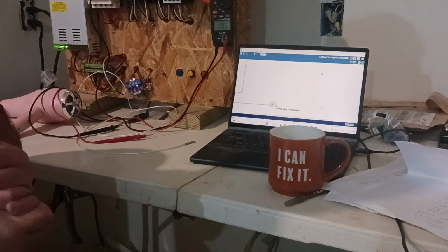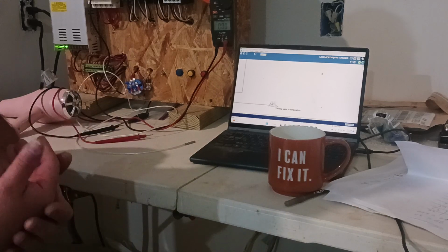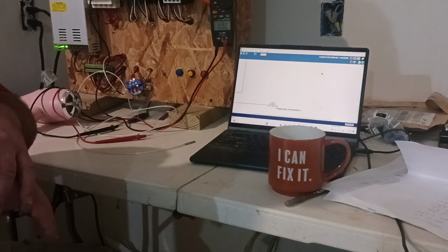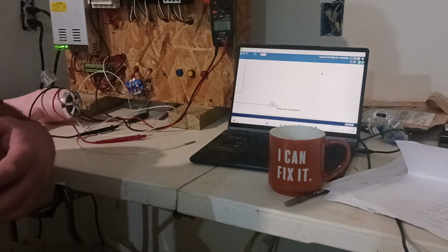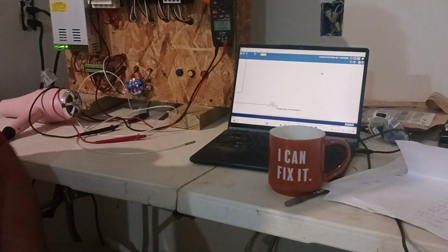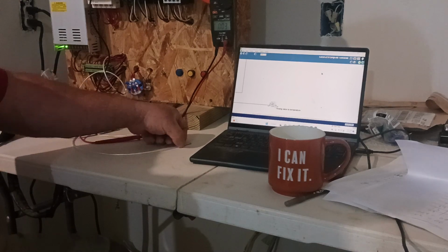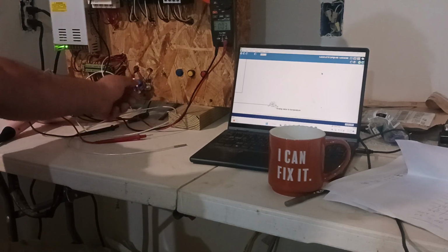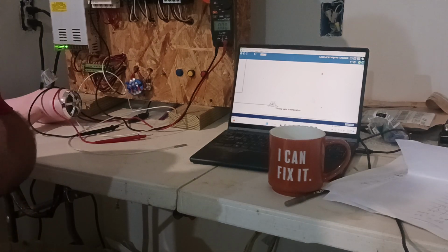Now also know that analog is not only input, but there can be analog outputs. For example, with a VFD, you want to select the frequency to change the speed of the motor, and the wires sent from the PLC to the VFD are analog, so the stronger or weaker the signal gets, the frequency is more or less, and it changes the speed of the motor. Like I say, you can have inputs and outputs. Inputs would be like temperature sensors, pressure sensors, even turn dials like this potentiometer, and outputs would be something like speed of a VFD.